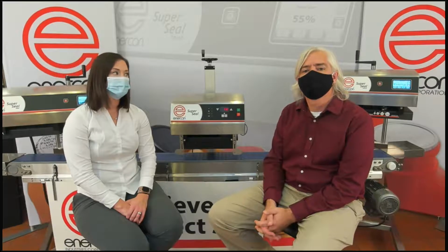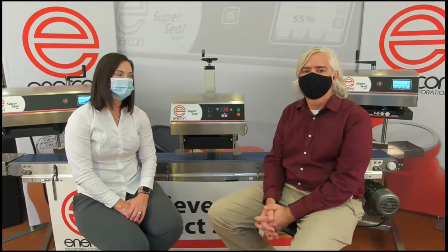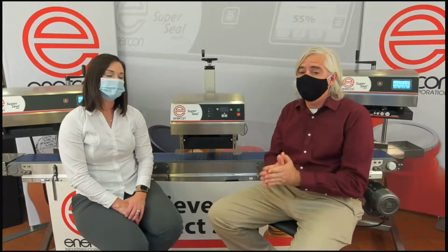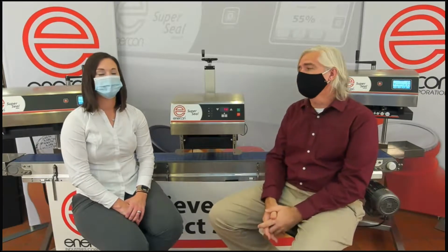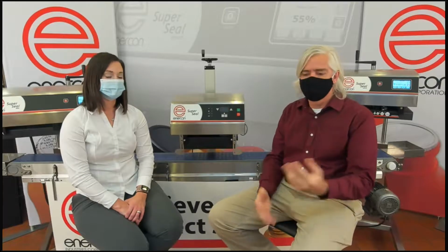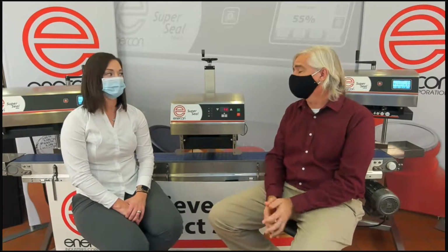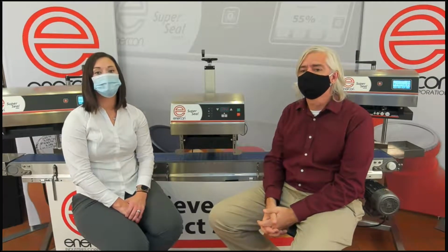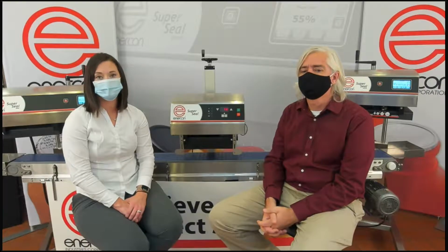So it looks like the lack of cap application torque can be a big problem, even if you have the rest of the system set up properly. Yes, that's basically the number one cause of leakers, just inadequate or insufficient or inconsistent torque. I believe our next video shows how lack of torque can be a cause of a partial or inconsistent seal.